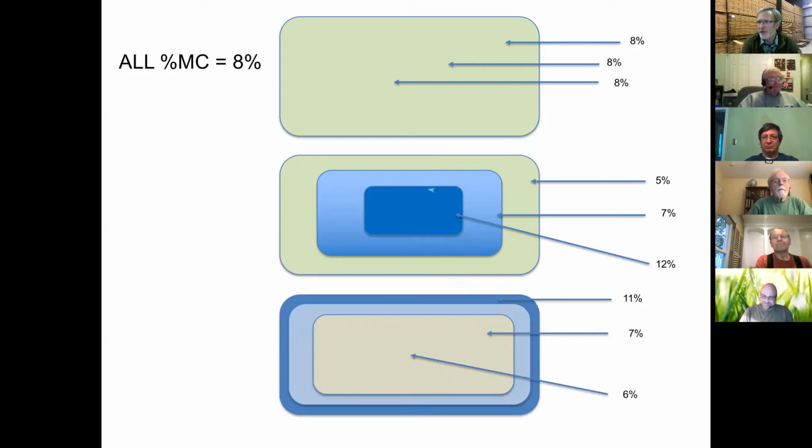Well, what do you think happened to that wood when it was in the shed outside for 6 months? It's still dry. It still says it's at maybe 8%, but now the inside is actually closer to where I wanted it to be, and as you move to the outside it can actually have picked up moisture. Why? Because the shed outside has a higher relative humidity than inside the house. And so that wood is actually going to pick up moisture.